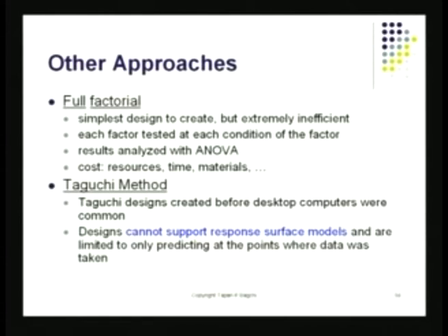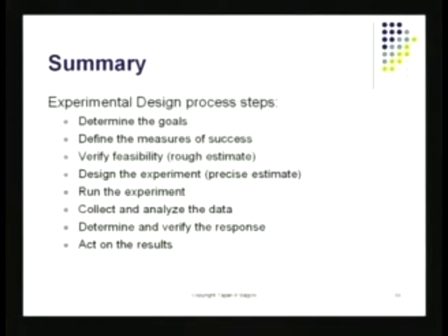For example, the full factorial method is there, like I told you earlier. The results of the full factorial trial are basically analyzed using ANOVA. Taguchi methods, on the other hand, lead to fairly simple, straightforward calculations. But the Taguchi approach to conducting experiments many times cannot figure out interaction effects between two or three factors, because most of these turn out to be partial factorial designs.